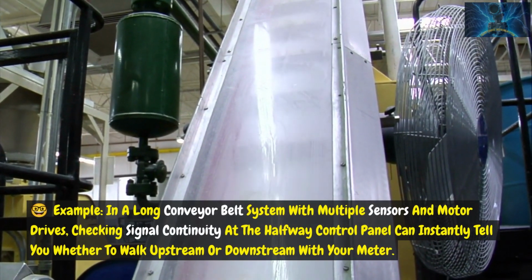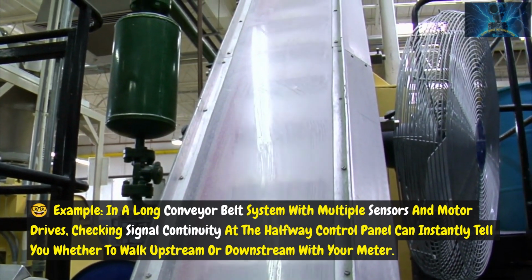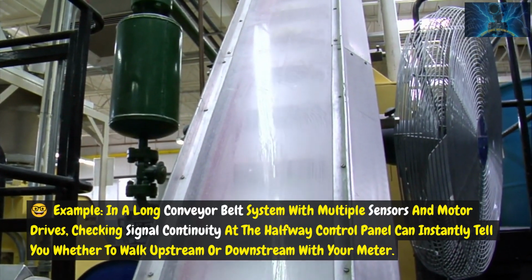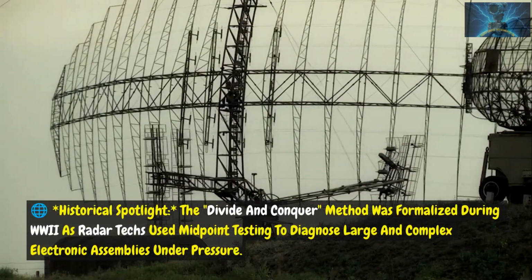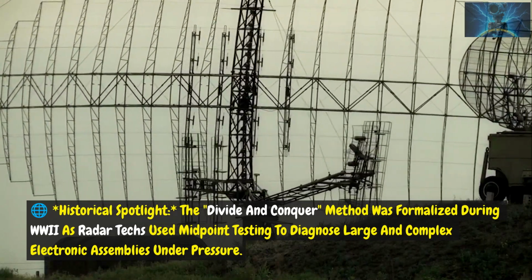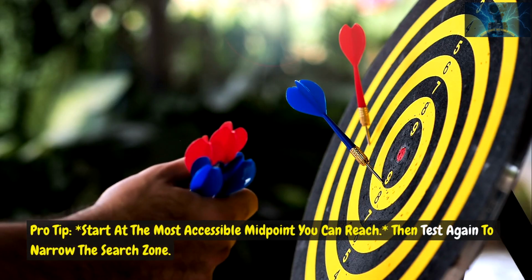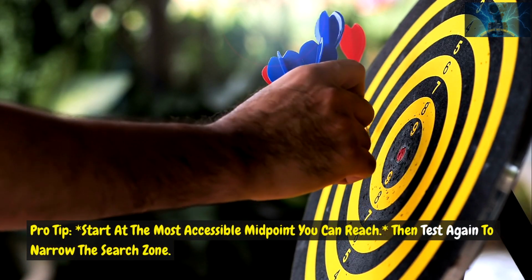Example: in a long conveyor belt system with multiple sensors and motor drives, checking signal continuity at the halfway control panel can instantly tell you whether to walk upstream or downstream with your meter. Historical spotlight: the divide and conquer method was formalized during WWII as radar techs used midpoint testing to diagnose large and complex electronic assemblies under pressure. Pro tip: start at the most accessible midpoint you can reach. Then test again to narrow the search zone.